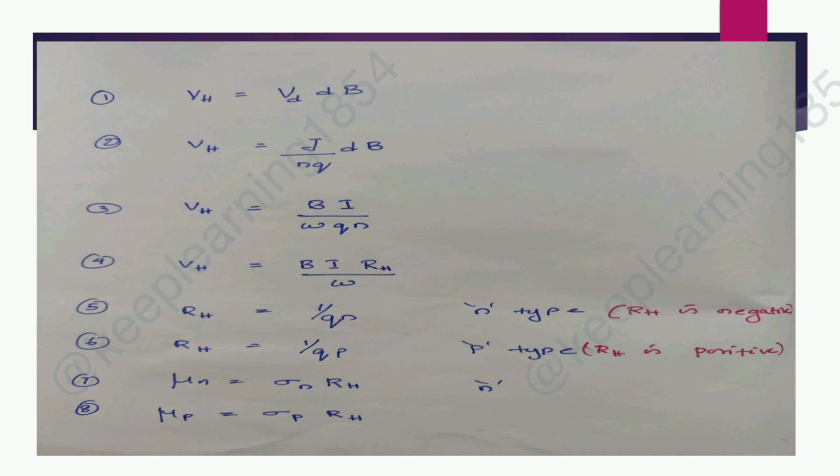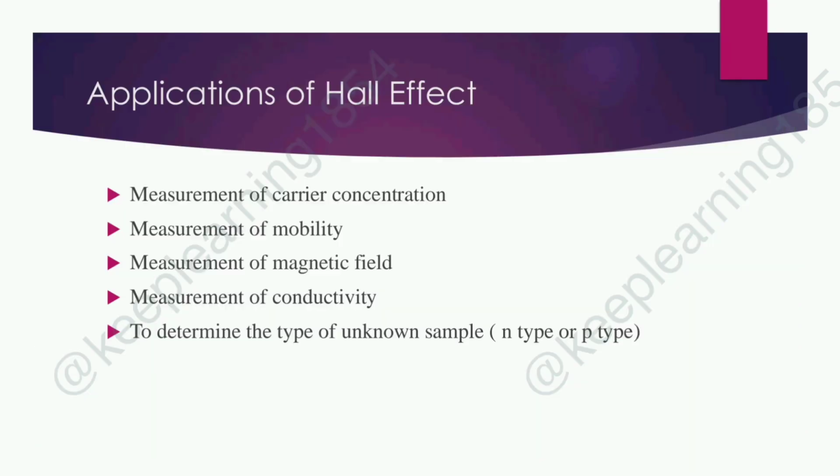Moving on to the applications of Hall effect. The principle of Hall effect is made use of in the measurement of carrier concentration, mobility, magnetic field, conductivity, and also to determine the type of a material, whether it is N-type or P-type. These are the important applications.